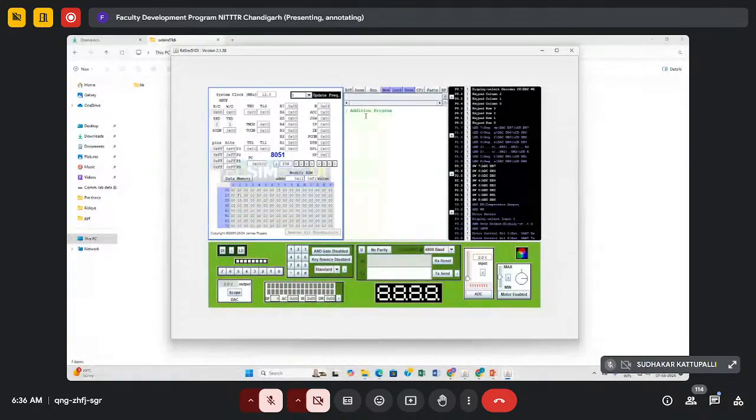There were various types of addressing which we were supposed to do. Let us do immediate addressing first. Suppose I write MOV R0. In order to do immediate addressing, in which we specify the data directly, we need to use a hash, as I told earlier.